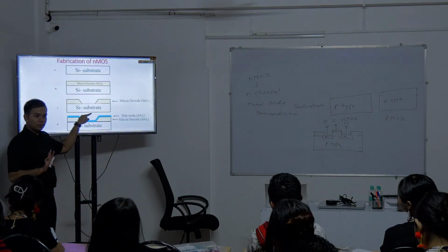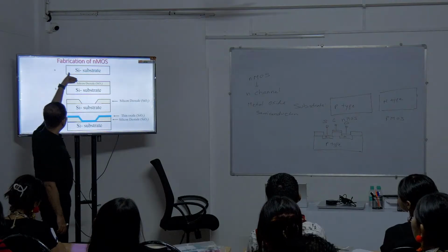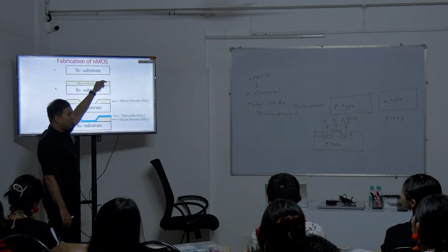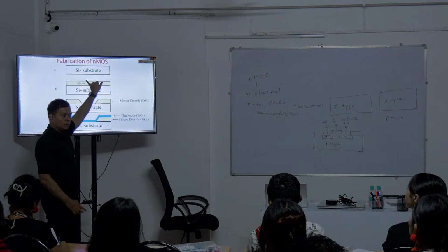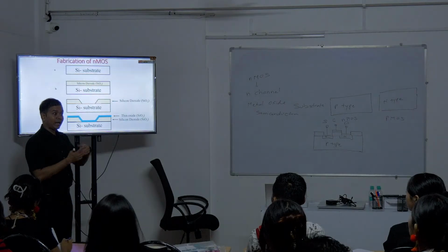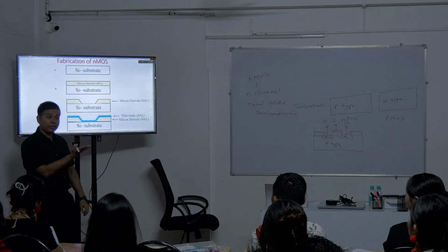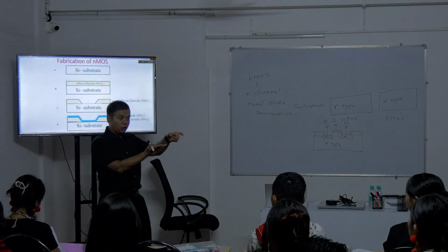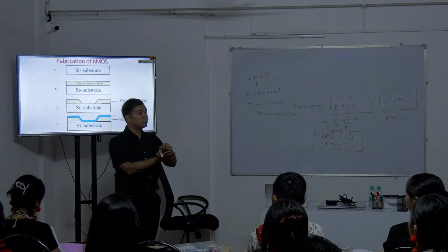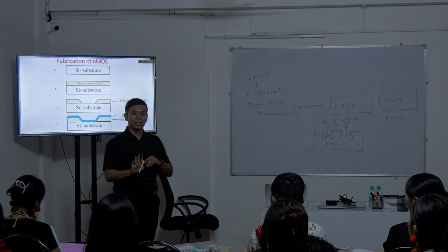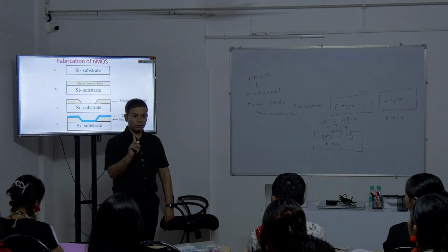Yes or no? So over here we put the mask on these two sides, while the center we kept open. And then we use the chemical which will get rid of the silicon dioxide. Whatever surface was exposed, not covered with the mask, will become soluble and you can easily remove that. Hope it is clear to everyone.